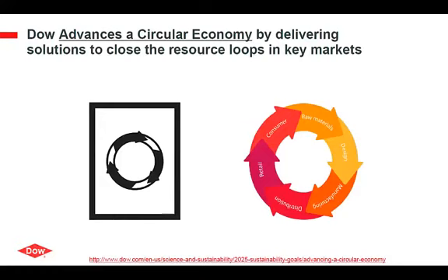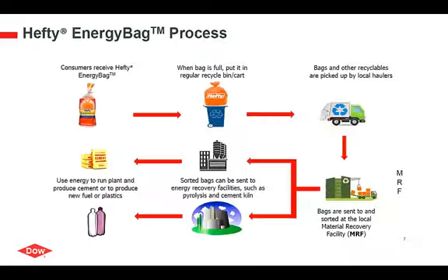One example of a step in the direction of a circular economy is the concept shown on the next slide of an energy bag. One of the key challenges to recycle plastics today is that many of them, particularly from packaging, are thin, flexible, multi-layer materials, and they are just difficult to process by conventional mechanical recycling technology because they're physically hard to sort and separate. And even if they're sorted, the fact they're a mixture of materials may mean that they're not compatible with other higher purity recycle flows, so there's less you can do with them.